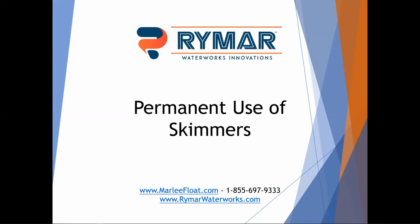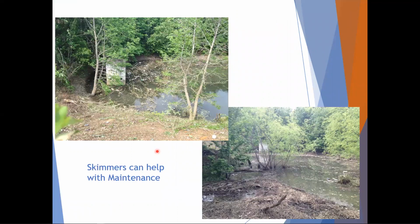All right, so we're going to jump into a little bit of discussion about permanent use of skimmers. Again, what we see is the low flow orifices that we're having to do for water quality on the post-construction side really get clogged and hard to maintain. So this is a pond where honestly they had not done maintenance in a long time. It was a mess, but it was a bigger mess than we realized once we got into it.